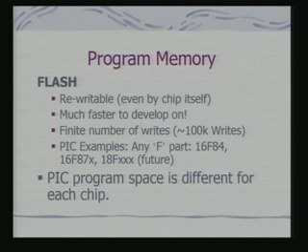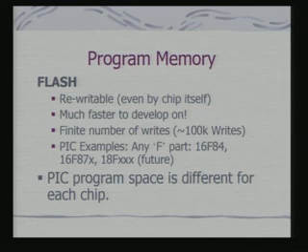That means I can get an appliance which has got a flash memory, and I can update that program in the flash memory even after I have bought the system and used it for a year. I get an upgrade of the software, and I put in the upgrade because I have got a system which is using a PIC processor with flash memory. This is the flexibility that the use of flash memory in the program area provides. And in fact, the program space for the PIC processor is different for each chip, and this is an important point to consider when you are selecting a particular processor from the PIC family.